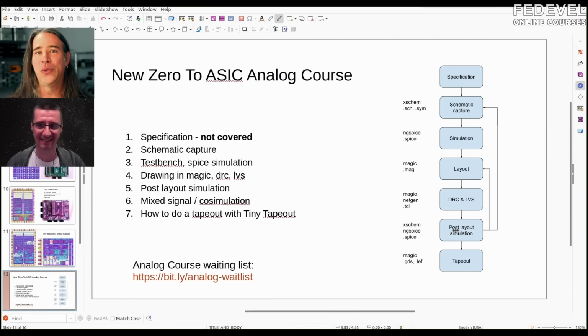And so you do that. And then if it's just too terrible, let's say you were going into some high frequency thing and you wanted this kind of reaction, but all this extra capacitance is just eating you away. Well, you're going to have to do something about that. And depending on the problem, you'll change metal layers, you'll shrink things, you'll move things apart, whatever it is. But then you have to go back to layout, do it again, loop. And that's why there are these little loops here in this flow chart, because you always end up going, oh no. The big loop is, oh, I have to go all the way back to schematic capture because I did it so wrong that something is terrible.